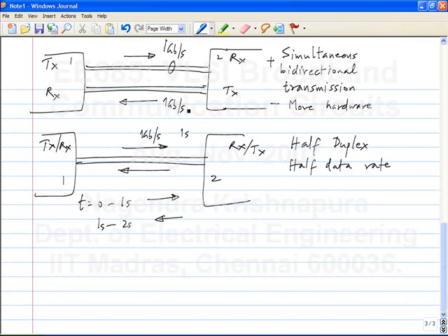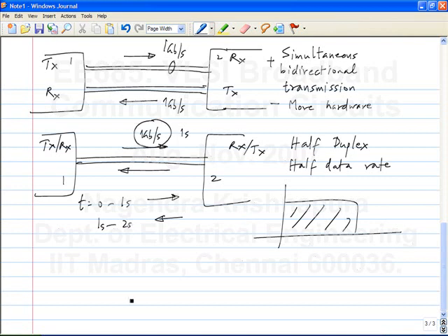Okay. So can we transmit data simultaneously on something like this? Well, let's say we don't want to do modulation because this is broadband data, right? So yesterday we said that the data spectrum looks something like this. It's not a narrowband signal. And again, we'll go into details of all this, how a link limits the data rate, etc. But when I say 1 gigabit per second, that means that I can't really go beyond this, meaning I can't go to high frequencies well beyond this one.